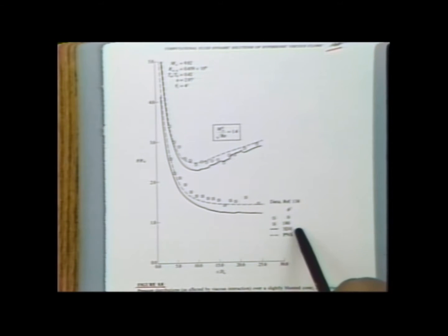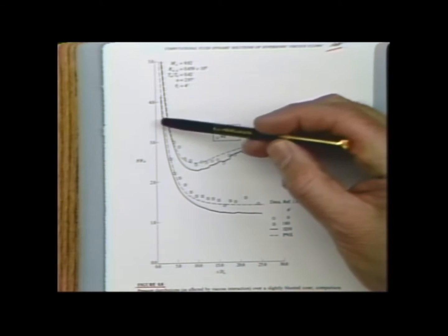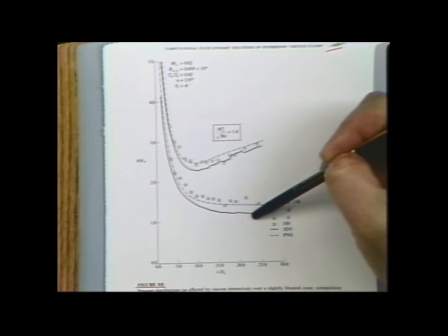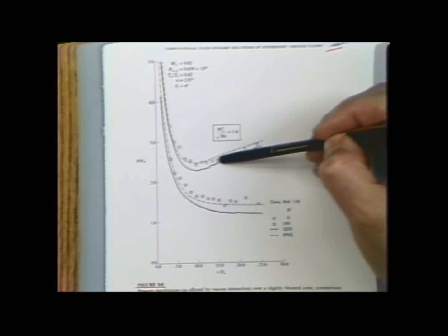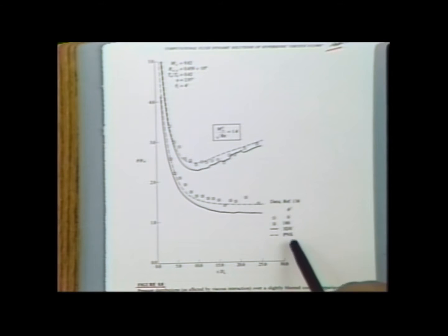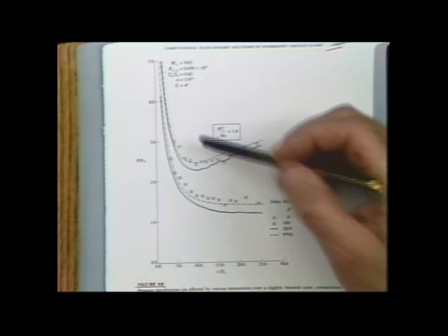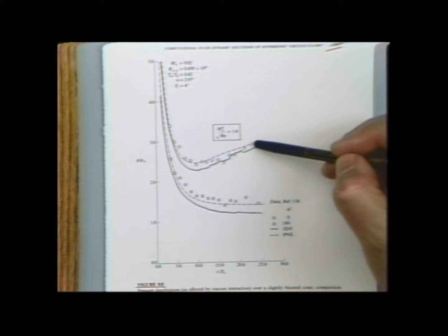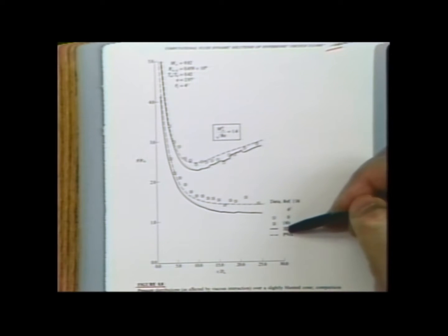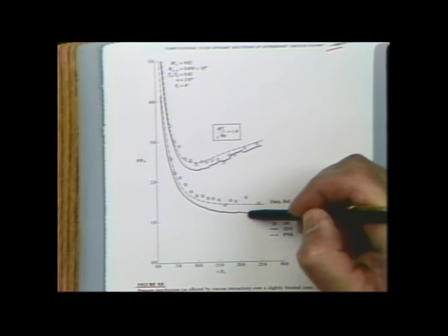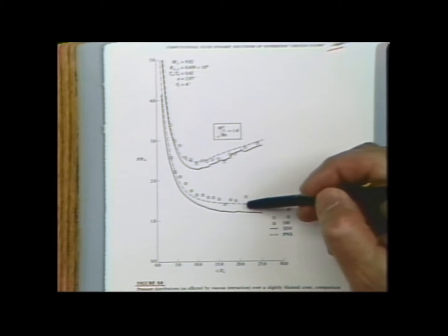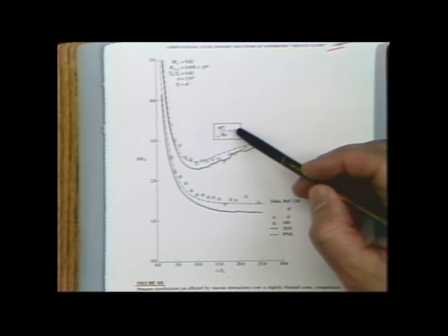Now the conventional boundary layer calculation, the 3dV, the inviscid flow with the boundary layer calculation, the solid curve here, gives us very poor agreement with the experimental data, especially on the leeward side. Pretty poor agreement here too on the windward side, except for these points here. On the other hand, the parabolized Navier-Stokes solutions agree fairly well with the experimental data. Moreover, there's a big difference between the parabolized Navier-Stokes and the actual boundary layer type calculations. That difference is there in part due to the viscous interaction.